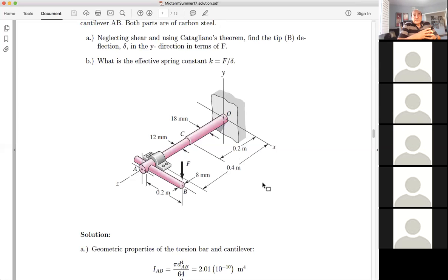The drawback of Castigliano, if there's one, is that we have to be careful in what constitutes the elastic energy stored in the structure. And once we find that out, then we have to take a derivative of the elastic energy with respect to the force under which we need the deflection. So conceptually, it sounds simple, right? But the implementation needs a little bit more practice. It basically needs a few problems solved, so we would know how to do it quickly.